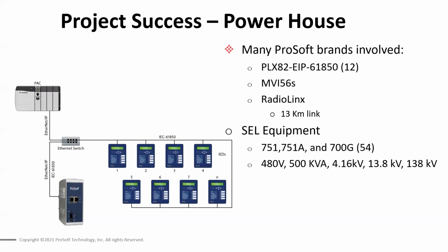So there's a question about backplane comms too. I believe that means the IO. On the gateway module, the IO connection is directly through Ethernet IP class 1 IO. And then on the backplane side, in the ControlLogix module, it's very similar.